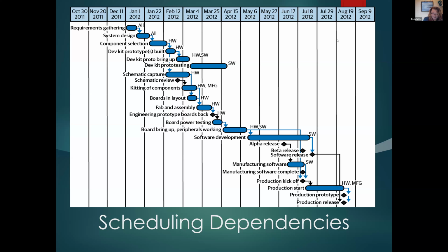The software development and debugging time gets compressed when things go badly in the hardware design and manufacturing stages. This is just the nature of the business. There's just not much you can do to change it, except one thing. That is, all the free time in the schedule can be used to create hardware tests that can be used to verify things in manufacturing and during board bring-up. Though that goes back to you thinking about you as a software engineer that may not have been part of the whole process.